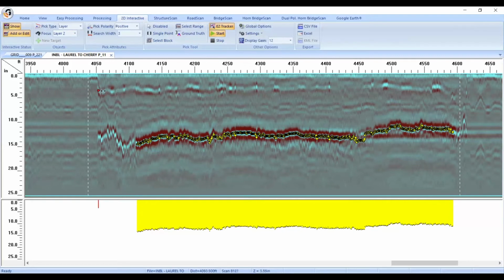So I left click to add one dot, I left click over a little bit to add some more dots, and I'm clicking, and nothing is happening. So what's going on? Why can I not add targets over here? I can't add targets over here because my focus is currently on layer 2, and layer 1 exists below it.